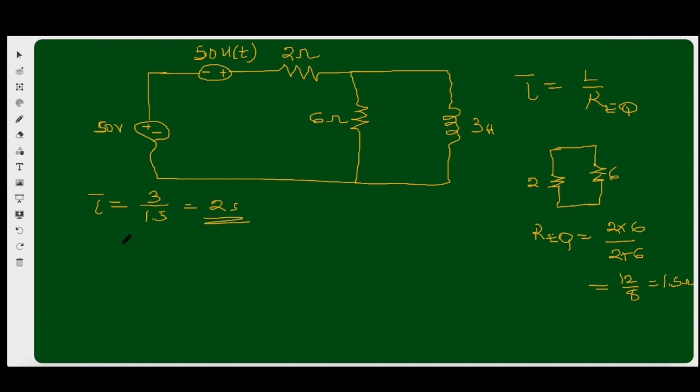So, what is the current? The question is that we should get the value of the current going through the inductor for all values of time in the circuit. I of t for all values that are less than 0 or greater than 0. So let's get the natural response because of course our complete response is the forced response plus the natural response.